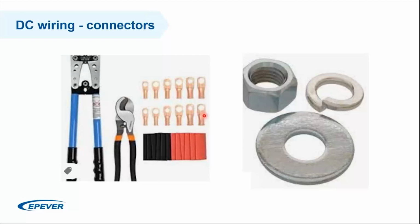The cable lock needs to match the cable thickness. So you cannot use any sort of cable lock with any cable. You have to match them. Even the amount of the insulation that you cut over the cable is important. Then you have to use a special crimping tool to attach the lock to your cable. Sometimes I've seen people use unstandard tools like a hammer or so. It works at the beginning, but the problem with that kind of pressing is that the amount of the wire that touches the lock is actually lower than the thickness itself.